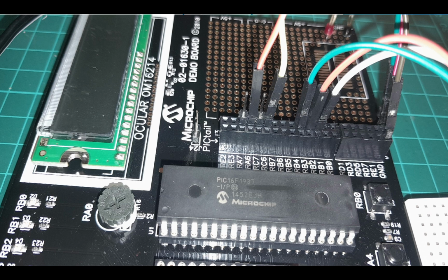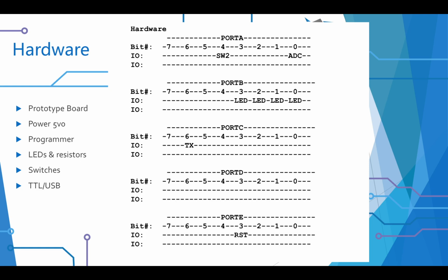They are very, very inexpensive, and we've gone through a lot of the capabilities. But what we're going to do is push one of these switches on the right-hand side, and we're going to make an LED turn on, called an interrupt. So the layout of that board is as per. There is nothing different about it. We have got a switch on port A. I'll just highlight that for you. Port A4, we have a switch. There's another switch on there somewhere else, but I actually don't have it on the diagram because I've not used it. And we're going to pick an LED here to do our magic. So whenever I push that switch, an LED is going to come on.